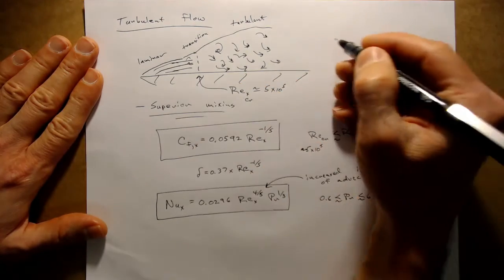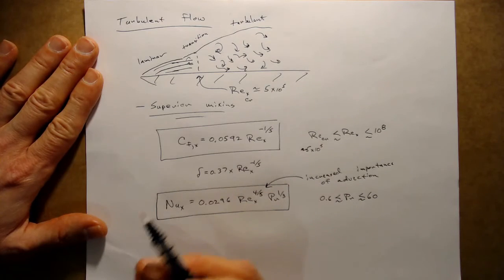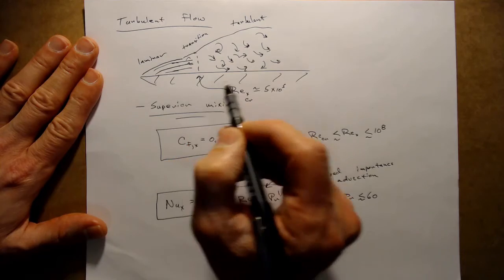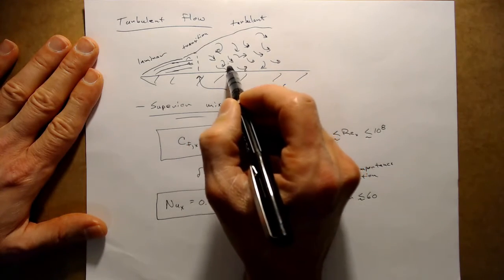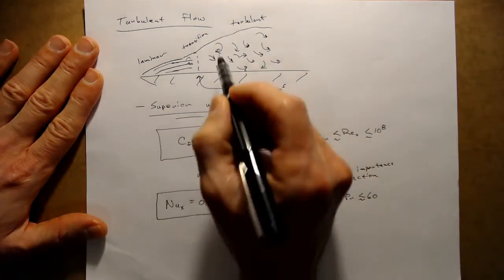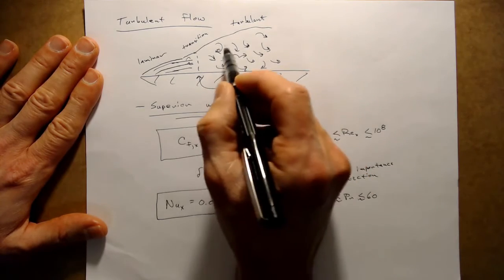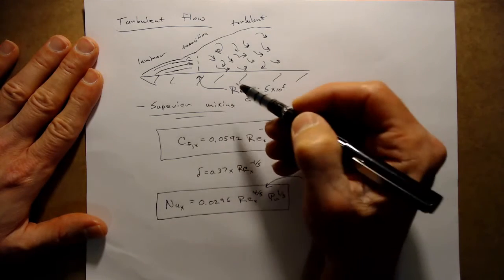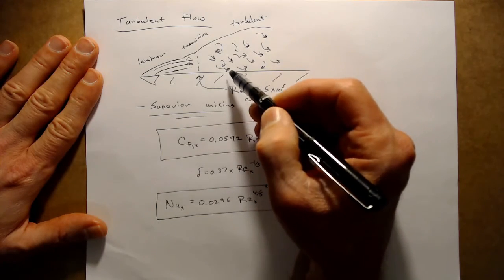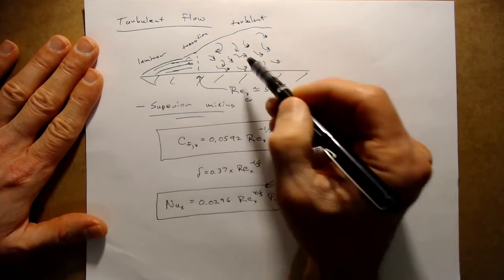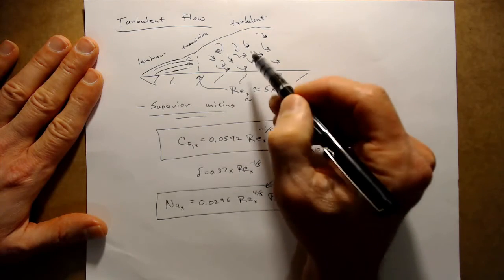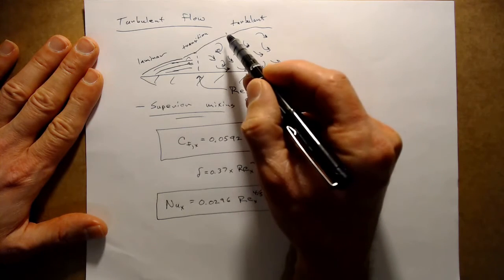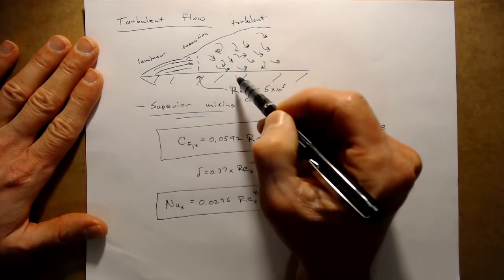And this turbulent flow occurs because the inertia of the fluid is now capable of overcoming the damping that corresponds to the viscosity, and that allows packets of fluid to move around chaotically. And so we get this chaotic mixing behavior, where the flow is very unsteady, and there's a substantial y velocity, or velocity along the y direction, that's able to push momentum and thermal energy from the free stream to the